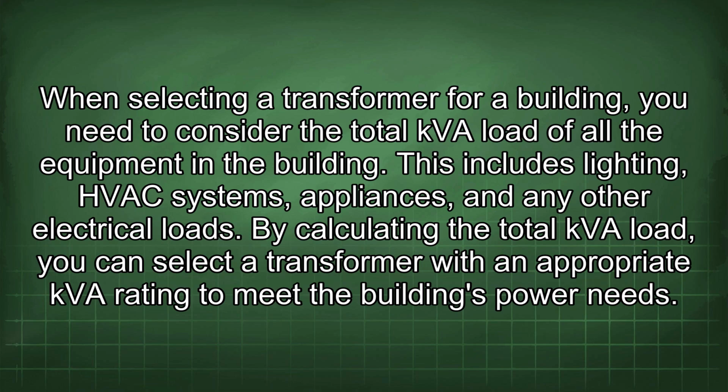When selecting a transformer for a building, you need to consider the total kVA load of all the equipment in the building. This includes lighting, HVAC systems, appliances, and any other electrical loads. By calculating the total kVA load, you can select a transformer with an appropriate kVA rating to meet the building's power needs.